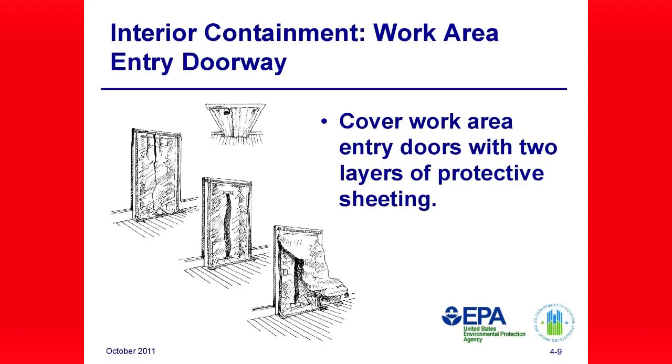For exiting and entering the room, tape a vertical line about the size of a man from the floor to the header of both sides. Cut a long vertical slit through the tape in the middle of the protective sheathing. Leave about 6 inches at the top and bottom uncut. Reinforce the top and bottom from the slit with tape to prevent the plastic from tearing.